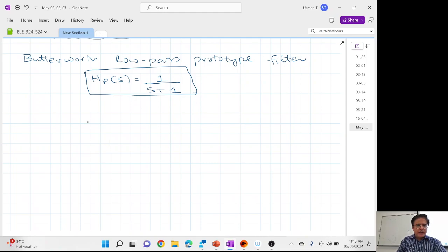So if you have the transfer function in the s domain and you want to get the frequency response, what do you do? Yeah, exactly. You just evaluate the transfer function on the vertical axis, right? Let me use the variable nu for the frequency. So I can just substitute s with j nu, to evaluate the transfer function on the vertical axis.